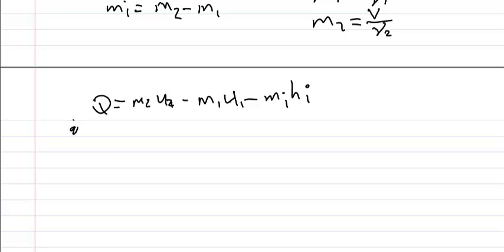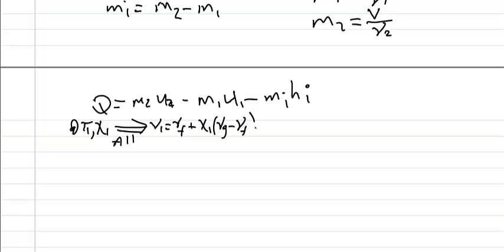So at the initial conditions, at T1 and at the quality at 1, here, for this two-phase mixture, we'll have to go into table A11. Let's find the specific volume first. So the specific volume V1 is just VF plus the quality at 1 times VFG. As usual, our textbook has no VFG data, so we'll just find it by taking the difference between VG and VF. So let's just pull the data out of our table.